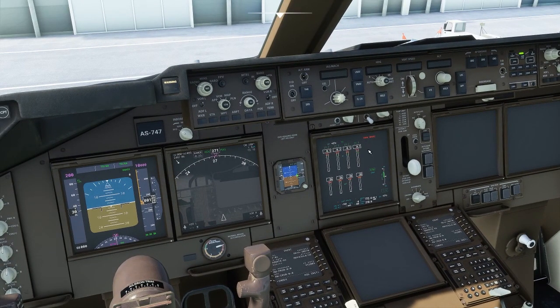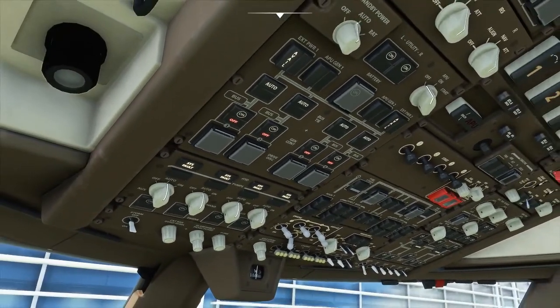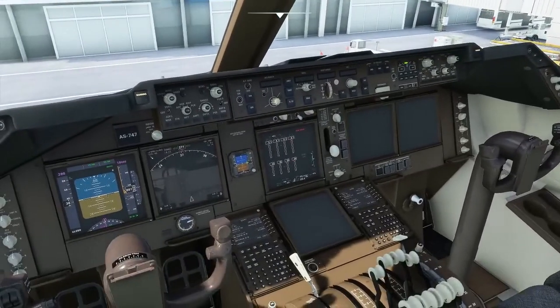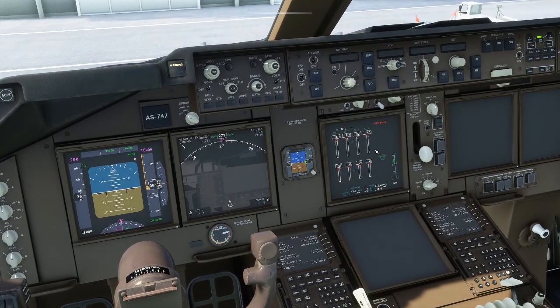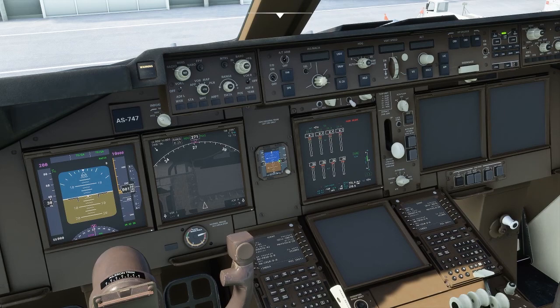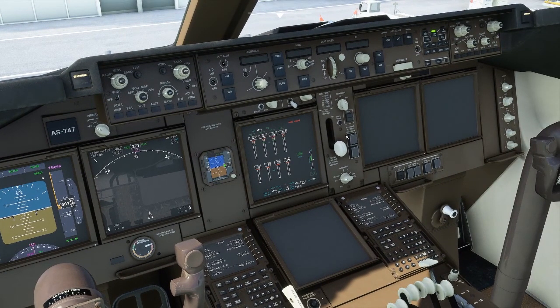The selection of the switches means that if you lose all your AC power, so your generators from engines or APU, your DC batteries, so your direct current batteries, which don't have that much life really in them, I think it's a minimum of 30 minutes that they need to operate for while running these systems. So they'll display these screens. They're on standby power basically, so if all else fails, then you can run these off battery power for a while. And if you have the switch working, you could flick it over, and then the first officer would have these screens instead.